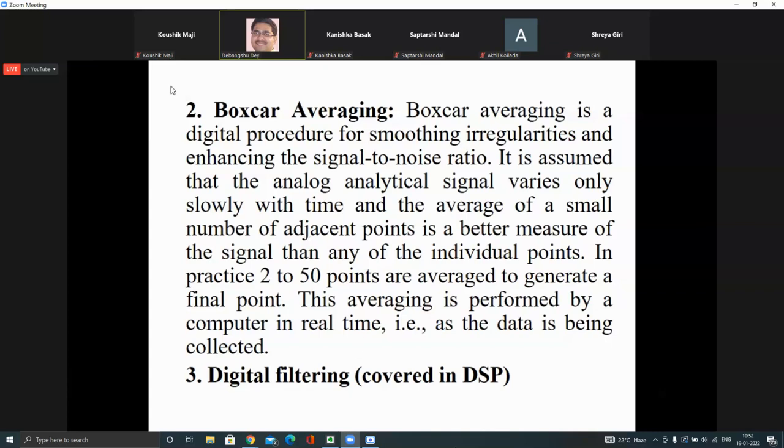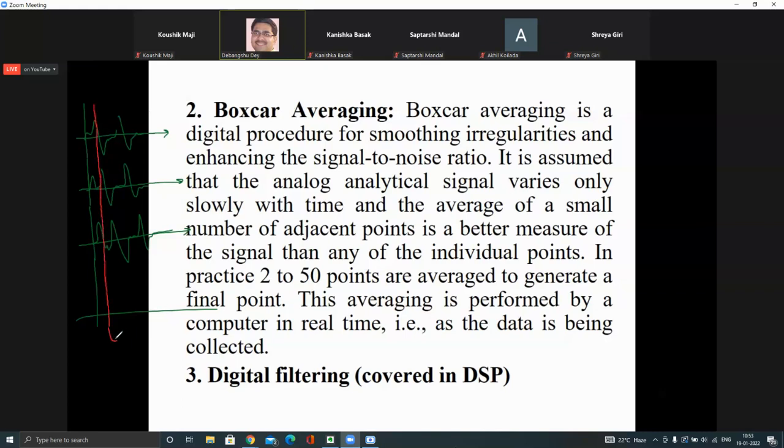Now the ensemble average is something different. That means say you are able to record your ECG signal many times. The same ECG of the same person you have recorded say 100 times, 50 times, 20 to 200 times, whatever is possible. Ensemble average means you are taking the average. Say this is time t. You take at time t the sample values of all the realizations, take the average and put it like this. Then take another time instant.